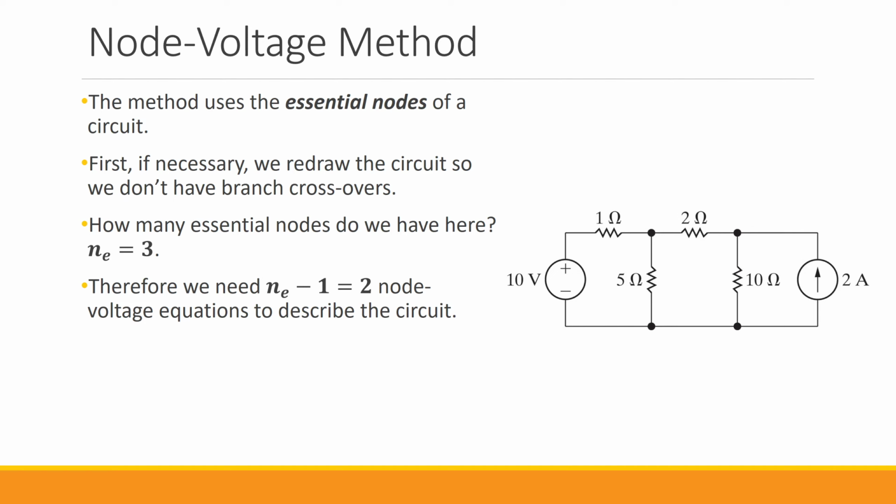So even though the systematic approach is very good, we said that we need to make some changes to the variables that we define. If you remember, for any component in the circuit, we use either their voltage or their current for solving that circuit. But we said, what if we change those variables? Instead of going for voltages and currents of individual elements, we go for voltages at essential nodes, or we go for currents in meshes.